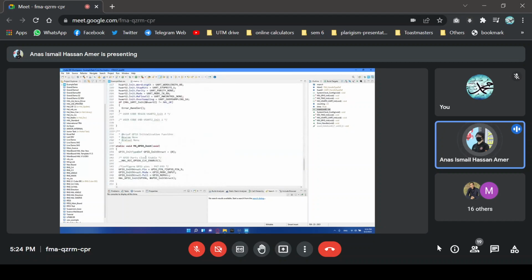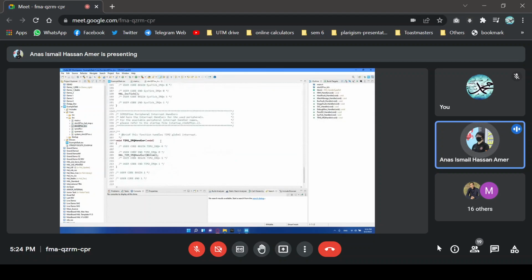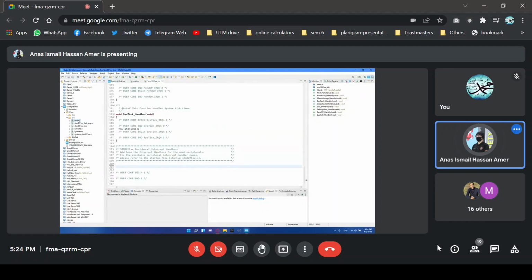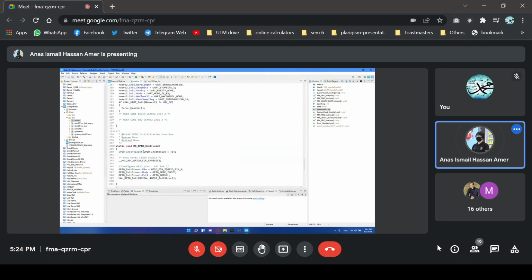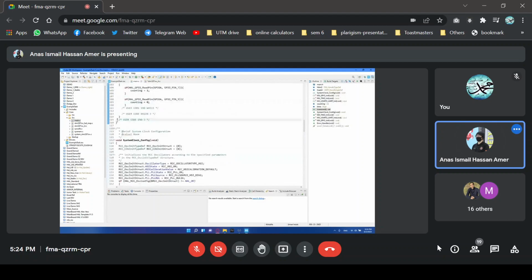So let's see inside the timer itself. If you go to the example task and then go inside our IT file, which is the interrupt file, scroll down, you should see our timer 2 IRQ handler. One thing you can do, instead of including your definition here, is just cut this and put it inside main, directly under the main function.